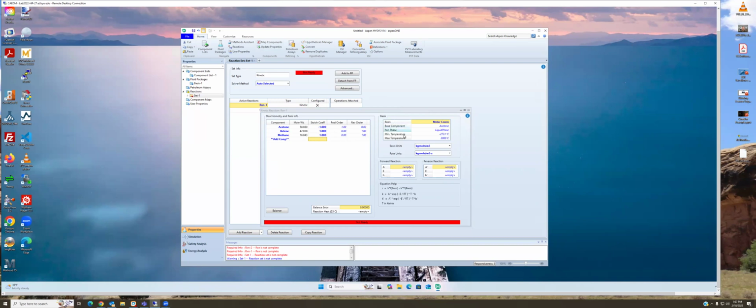And come over here to this basis window. Basis is molar concentration, and that's what we want for this reaction because those are the units that our reaction expressions are given in. The base component will be acetone. We know that this is a high temperature vapor phase reaction, so we need to change that phase.